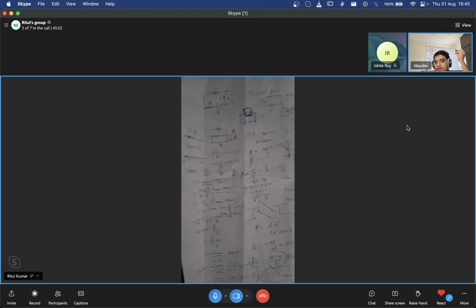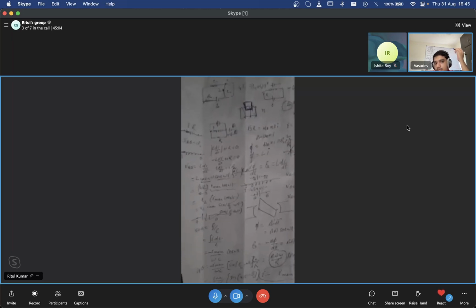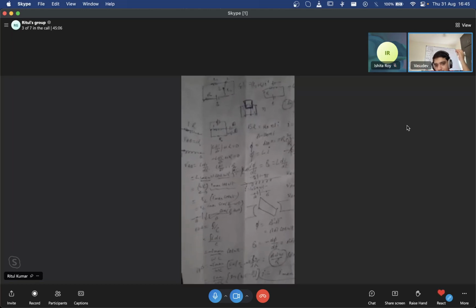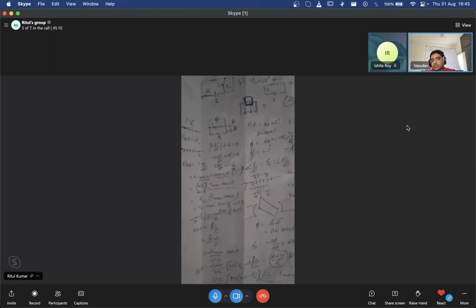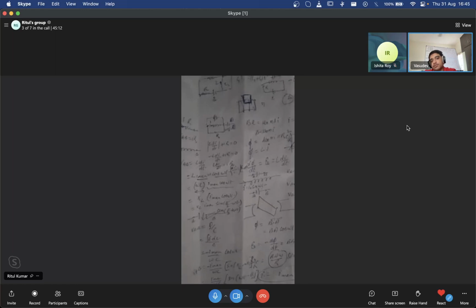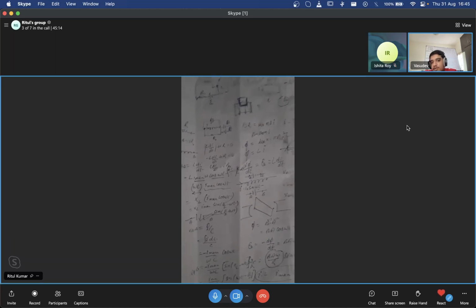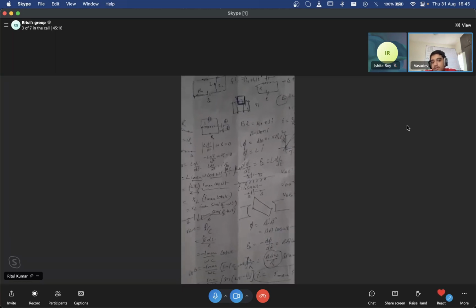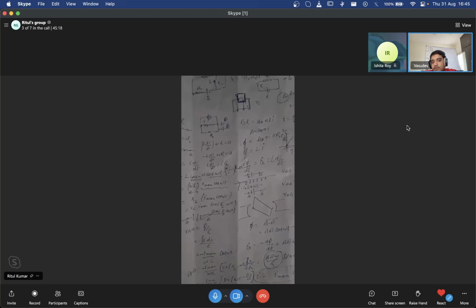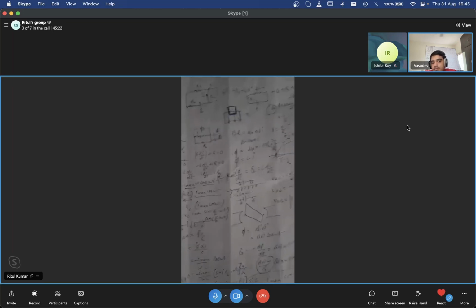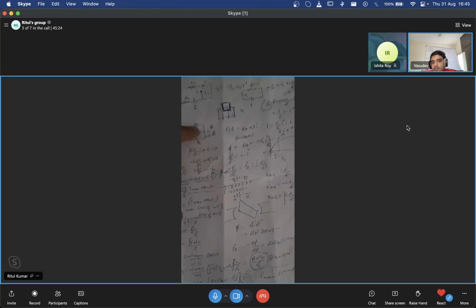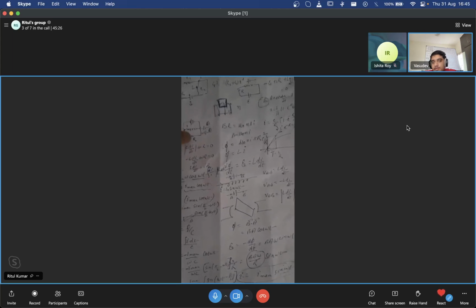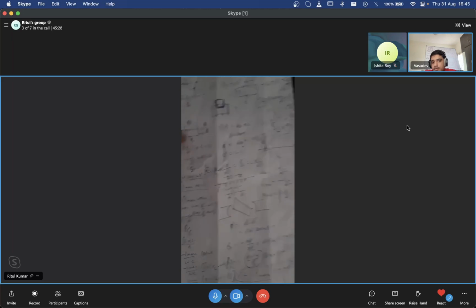But then I'm with mod, plus minus both. But yeah, that does work. But you've got to take a specific direction when you apply Kirchhoff's voltage law, right? So, for example, I could have gone the other direction. I would have gotten IR to be negative, and L di by dt would have been positive. Yes, correct. But it'll end up getting the same. Which way do you want to go? This way or that way? Clockwise, anti-clockwise? You'll be getting the same equation. How will it be different from this equation?